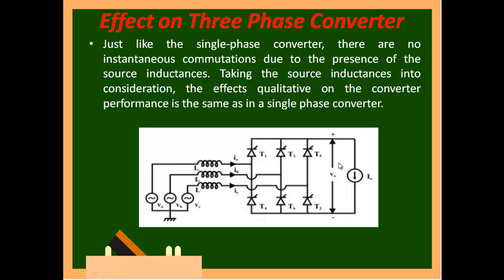I think you might have studied in machines that the issue of phase to phase is worse compared to phase to ground. So phase to phase is worse than phase to neutral. Phase to ground is a 230 short, phase to phase is a 415 short. Think of a 415 short. When the 415 voltage tries to come to 0, think of the current which will be flowing, which will be 5 times the value, and even the insulator will fail. That leads to so many issues.